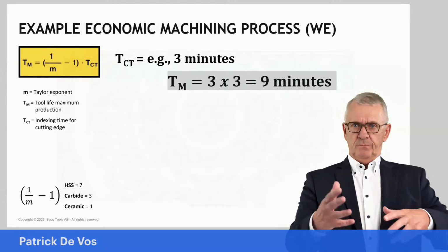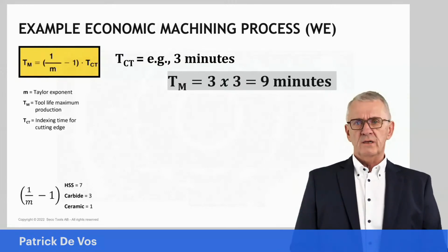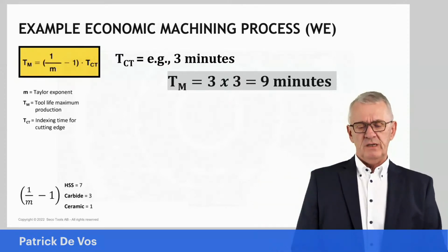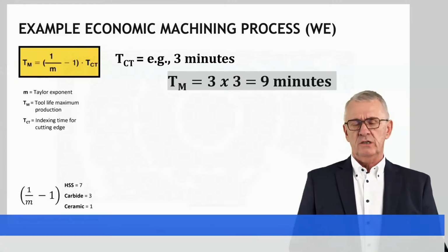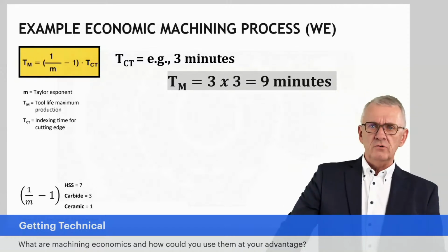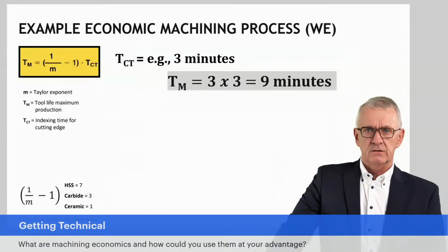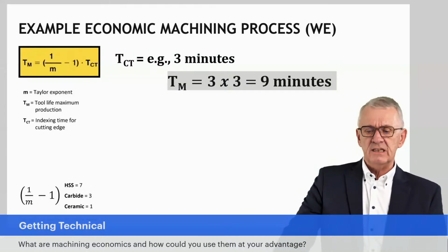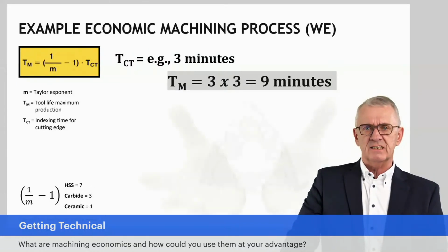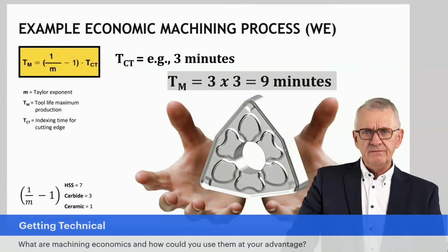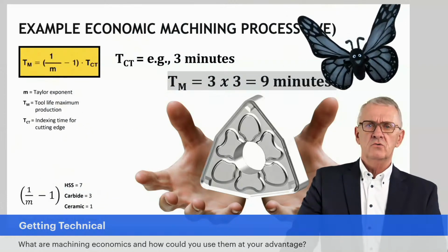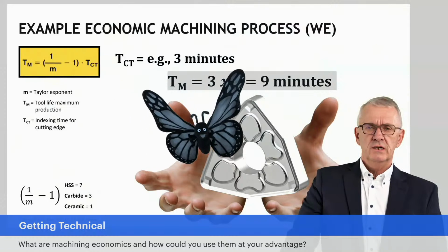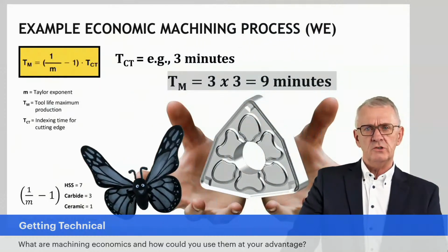Workpiece manipulation, you have a pallet changer. Tool manipulation, you have a tool changer. Automatic measuring cycles. People optimize their cutting conditions to have fast production, but the only thing left to be done manual is tool indexing. And it's that one single thing that drives productivity. You have it in your own hands. How fast or how slow you manage to change your tools is deciding how productive you are.